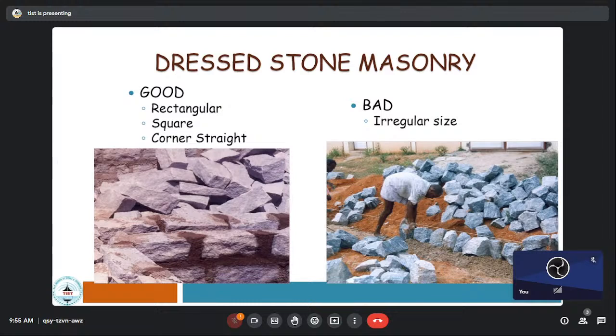So like that, you would have noticed, knowingly or unknowingly, a good mason who is working with RR will knock the structure using a hammer so that they will get to know whether the rock is good or not. And you can see here, this poor person who is doing work over there is just aligning the rocks. He is not shaping it. Now, what ultimately happens to such a structure? You will not have bone stones. The regular shape of that foundation would not be there. All this is going to affect, including the aesthetics of the structure. Am I correct or not?